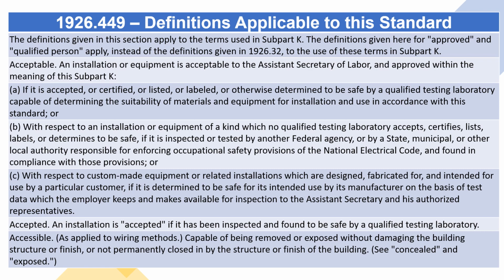Accepted. An installation is accepted if it has been inspected and found to be safe by a qualified testing laboratory. Accessible. As applied to wiring methods. Capable of being removed or exposed without damaging the building structure or finish, or not permanently closed in by the structure or finish of the building.